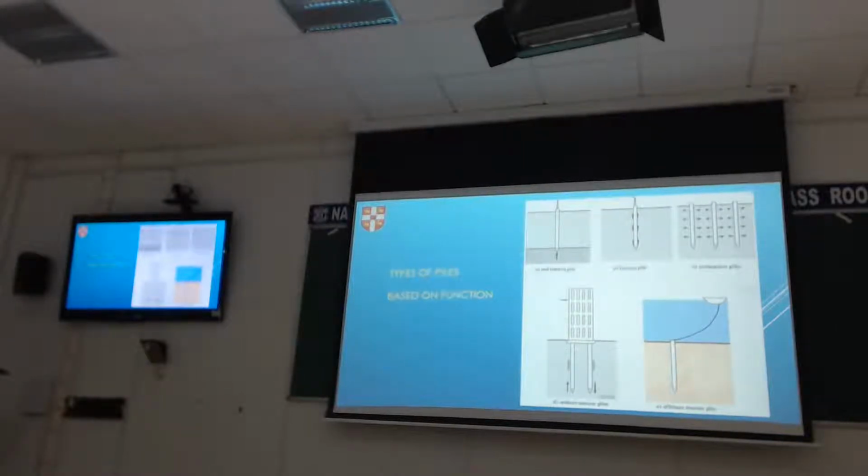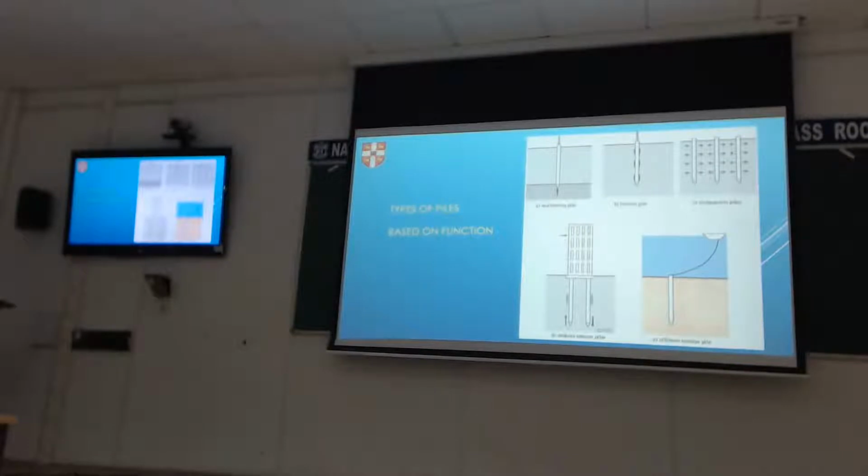The other application where you can get tension in your piles is the station box they constructed in Canary Wharf in London. The whole station box is below water. It's next to the wharf, obviously. Therefore, the only way they could keep the station box below water is by having piles underneath, because the box wants to float up, and the piles are holding it down. So they're all tension piles.